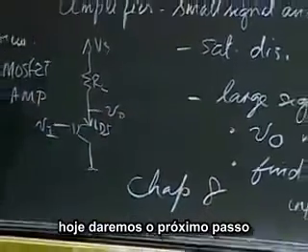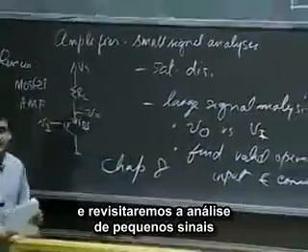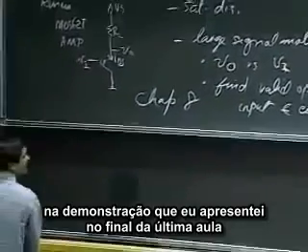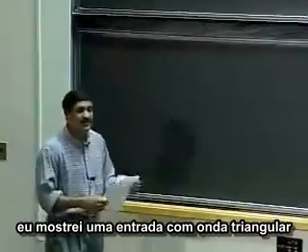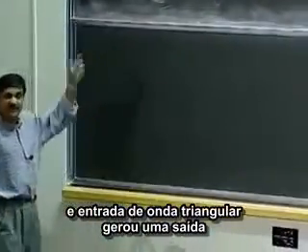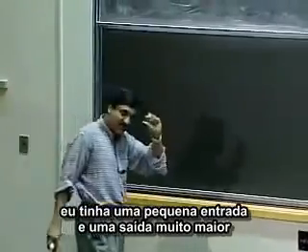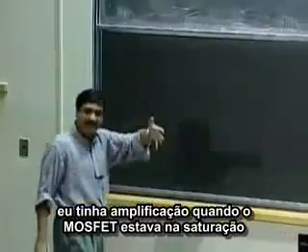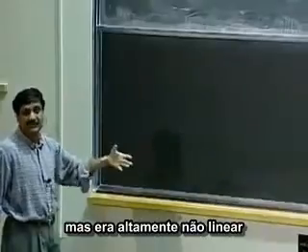chapter 8. And today, we'll take the next step and revisit small signal analysis. So in the demo that I showed you at the end of last lecture, I showed you an input triangular wave, and that input triangular wave gave rise to an output. And we noticed that we did have amplification. Okay, I had a small input, I had a much bigger output. I did have amplification when the MOSFET was in saturation, but it was highly nonlinear.